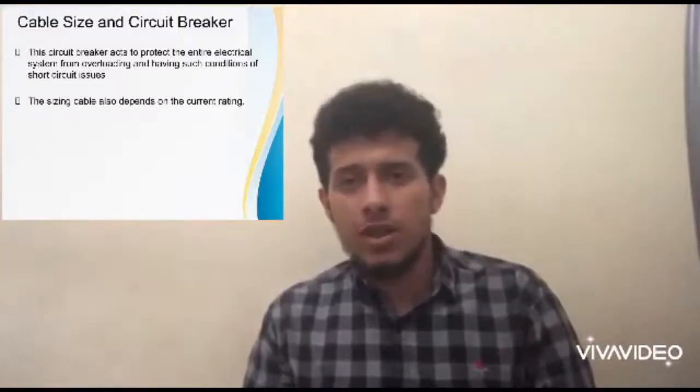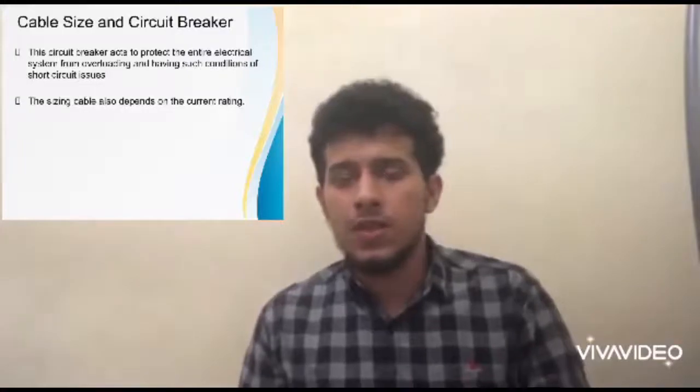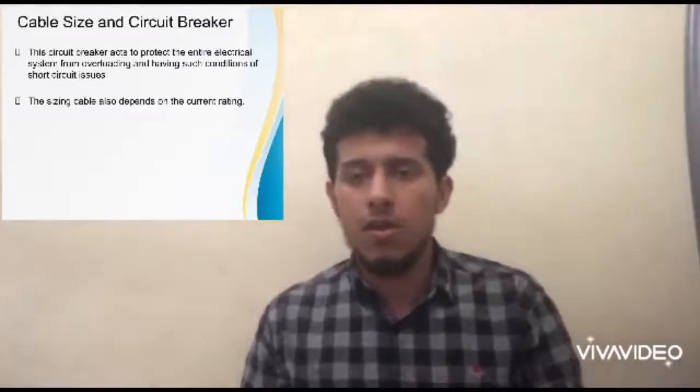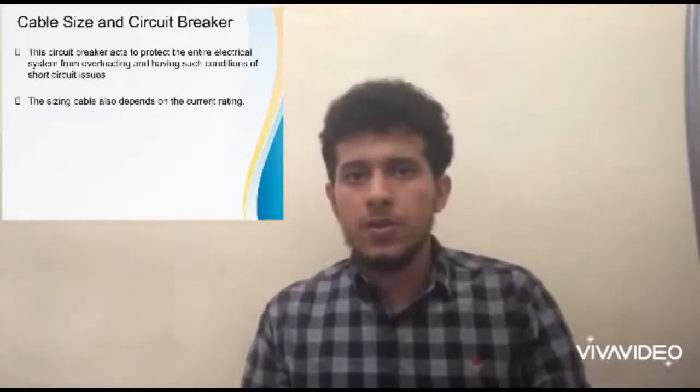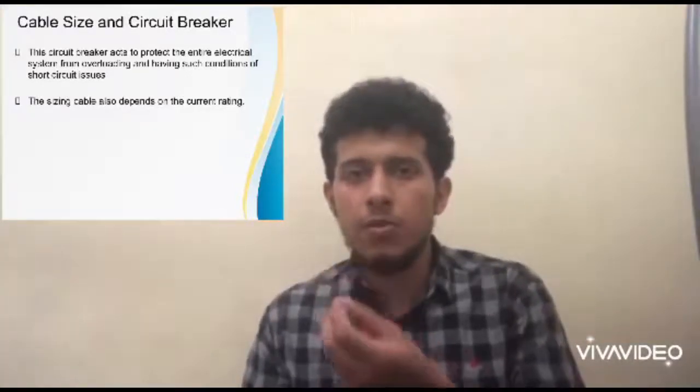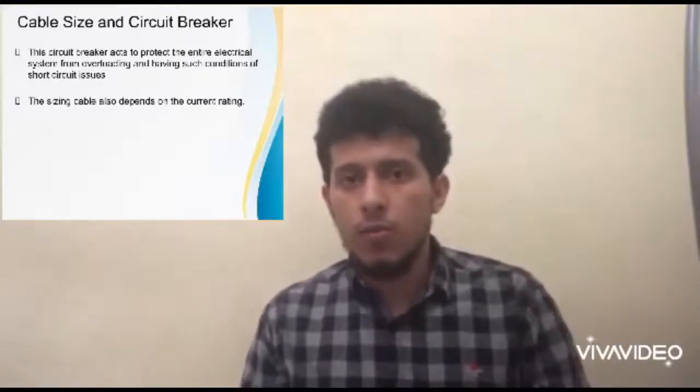The third thing is the cable selection. The cable selection needs to be considered carefully. The cable selection is based on the current rating. One of the requirements for the cable is that it must be able to withstand the heat produced by the flowing current. For this building, the current rating has been determined for choosing the suitable cable. The copper conductor cable with earth wire is proposed for this building, and we choose 4 types of size for this building.